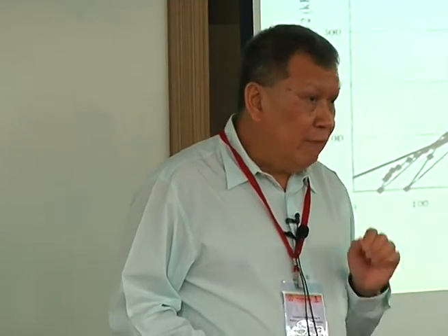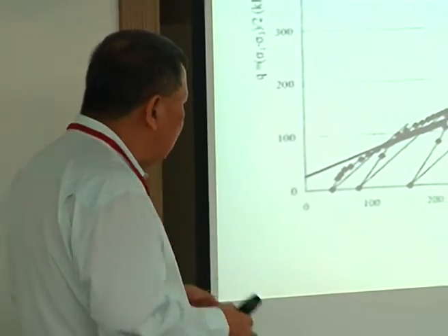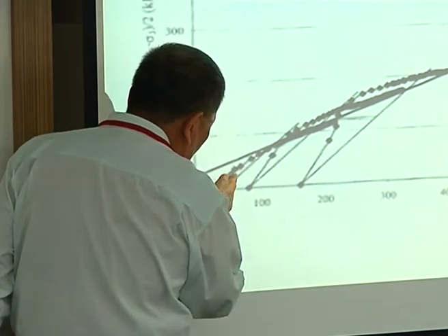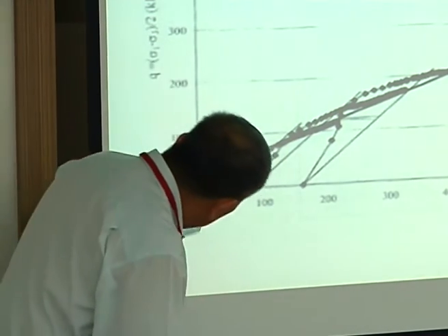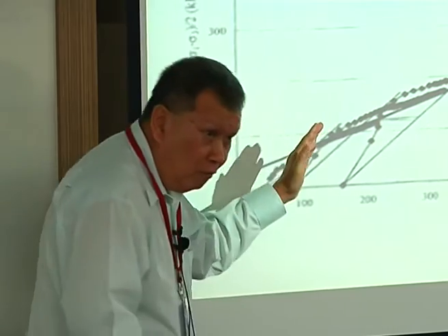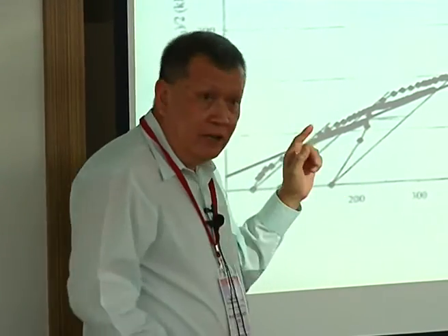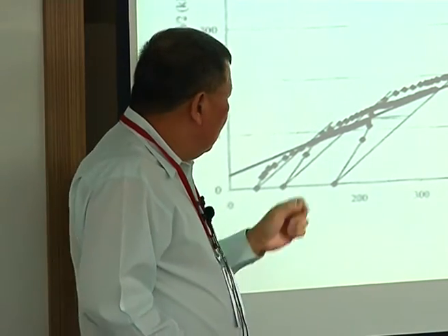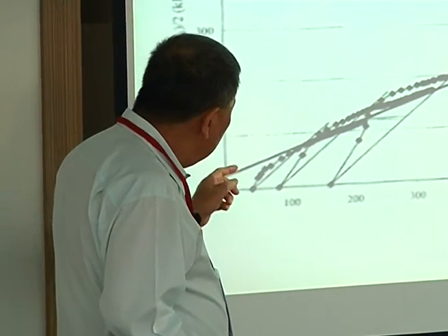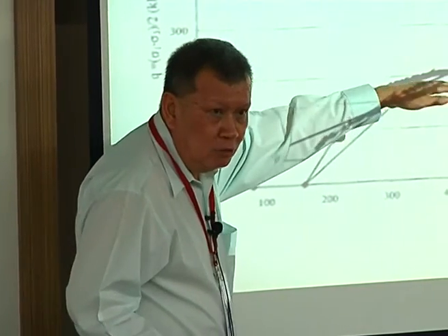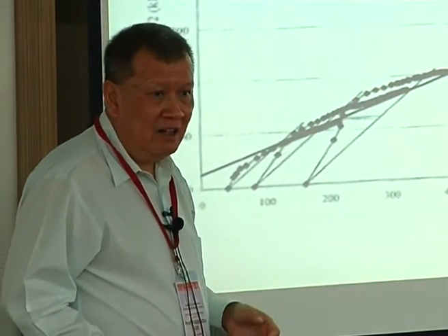All right. The effective stress is the other set of three lines. This has a gradient of 3 to 1, 3 to 1, 3 to 1. Right at the start, you can see just a little bit of 3 to 1, then it bends over. So these three are actually the effective stress paths. Now, you might ask, why is it that the effective stress path starts off so nicely and then suddenly just shoots over? Because the specimen yielded.